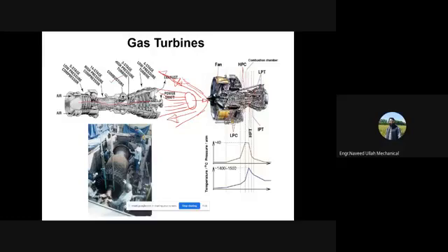All right, so the exhaust, instead of leaving the nozzle in the rearward direction, is now actually moving in the forward direction. So obviously as a reaction there will be a force applied on the engine and consequently on the aircraft in the reverse direction. And you know very well that if a force is applied in reverse direction to the motion of the aircraft, that is basically the brake. So the aircraft stops easily this way. That is basically the thrust reverser, right? It is present in every engine, whether turbojet or others.